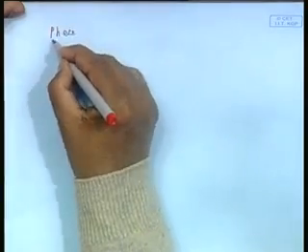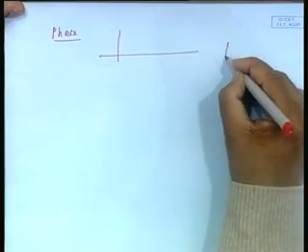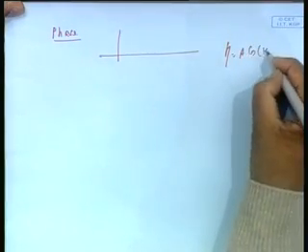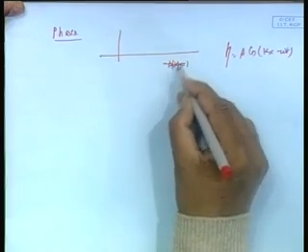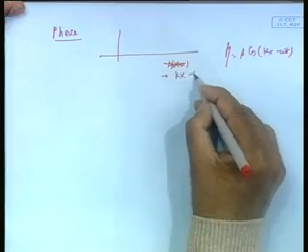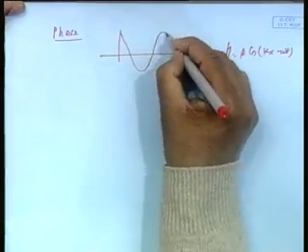Now, having said the energy part, I want to go to one more aspect which becomes very important when we study wave effects on floating bodies, structures, ships, etc. That is connected to the concept of phase. You see here, when I write an equation eta equal to A cos kx minus omega t, I can write this kx minus omega t here, and the graph looks like this.